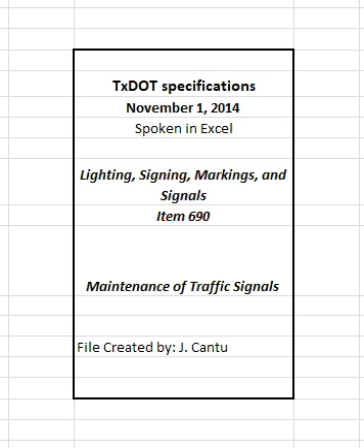Mount any or all of the following on an electrical service support assembly: conduit, weatherhead, load center, meter base, lightning protection, wiring, and associated hardware. 4.7 Signal pole. Install, repair, replace, remove, or modify signal poles in accordance with pertinent items, as shown on the plans, or as directed. Comply with Item 627, treated timber poles, for timber signal poles with guy wires and anchors, and Item 686, traffic signal pole assemblies, steel, for steel poles with concrete foundations.